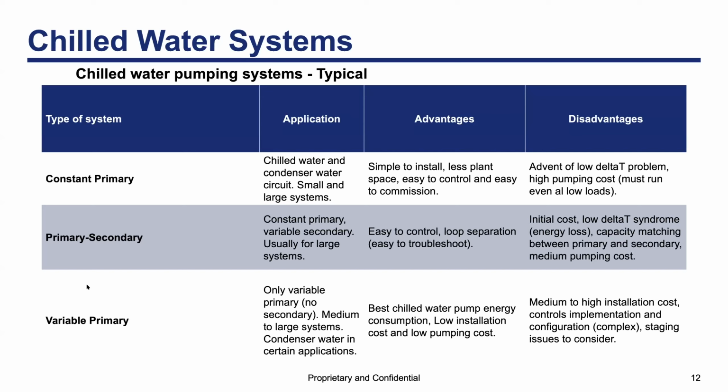Number one is water velocity. It shouldn't fall below 3 feet per second, or 2.5 feet per second. Below this velocity, whether it is 3 or 2.5, the flow is considered to be laminar, and the heat transfer effect is diminished, affecting the chiller's performance and, most importantly, the stability.